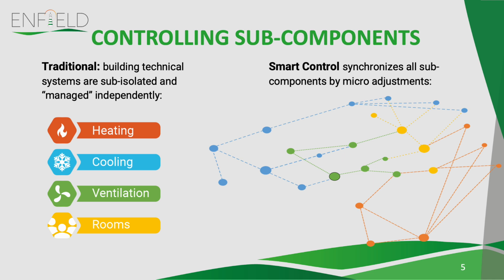Instead, we could heat maybe a little bit in the morning because we know that after that, in any case, it will be quite hot, and we can postpone the start moment of the cooling system, and it already saves a lot of energy, but it requires using more information, and it requires controlling all the devices together within one single control framework.